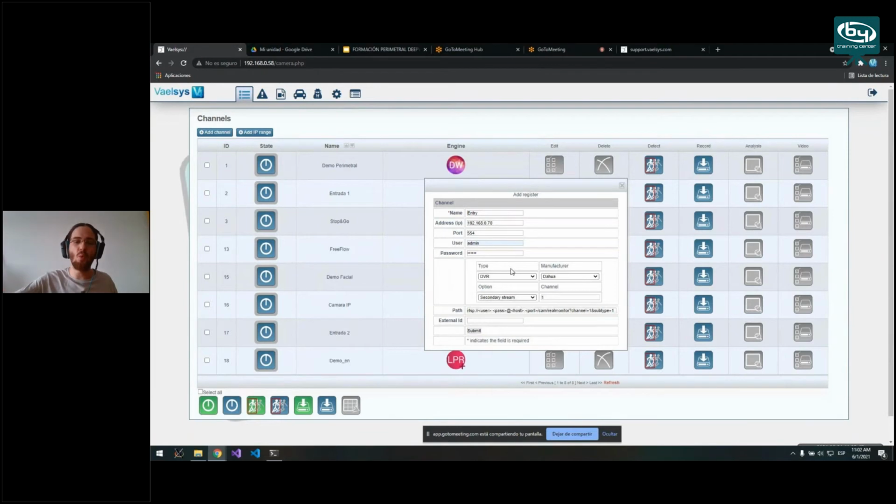This way, the camera will send the video to the DVR. The DVR will convert a secondary stream of this camera into a usable resolution for us, and then it will share the video with us locally. So the cable between the DVR or the switch and the camera will not need to transmit two streams, but only one.